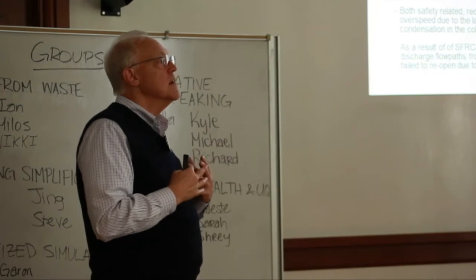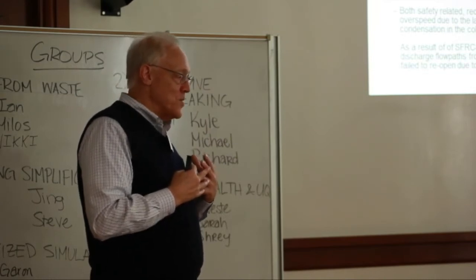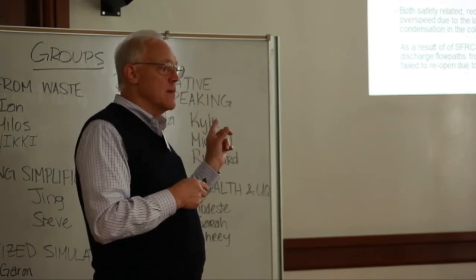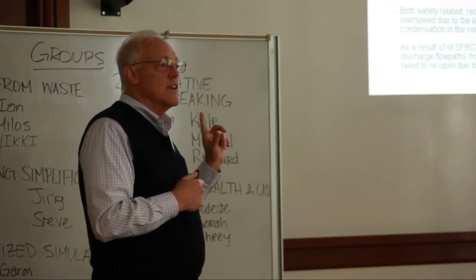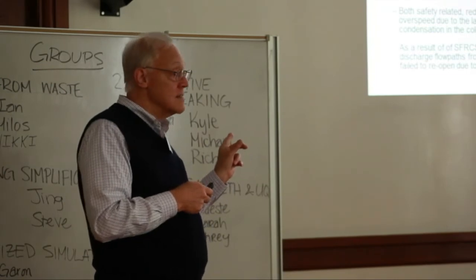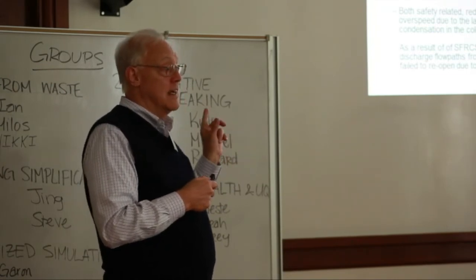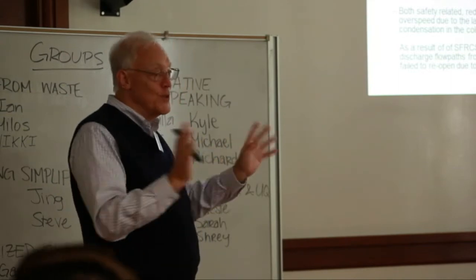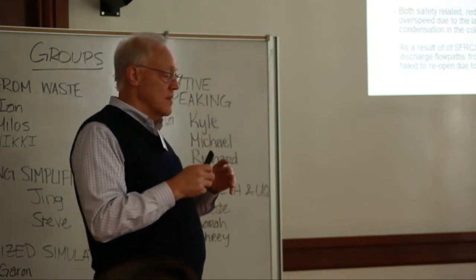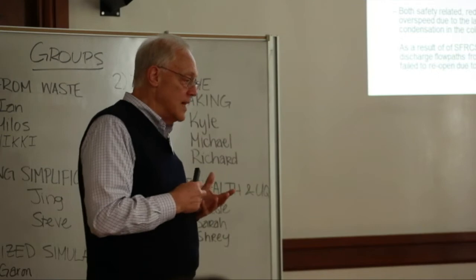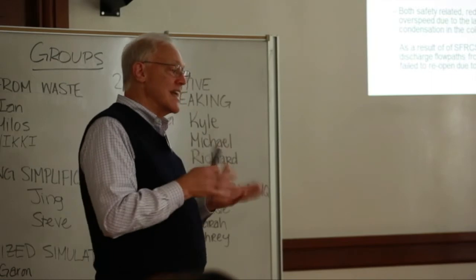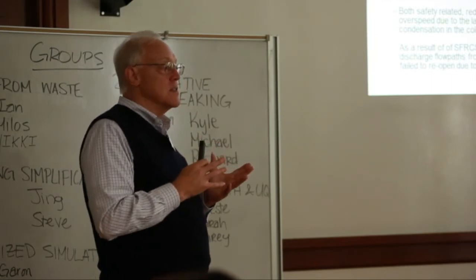One is, and Claire said it this morning, keep things simple. This is an exceptionally complex safety system. You really have to be clever to figure out how it might fail. And we hadn't adequately figured out how it might fail. It was licensed, it was reviewed, all the stuff, but we hadn't figured out how it could fail. In this case, the philosophy of this particular system, which was a core philosophy, was basically, if you think there's a break somewhere in the feed water or steam systems, isolate everything. It's called the steam and feed water rupture control system.